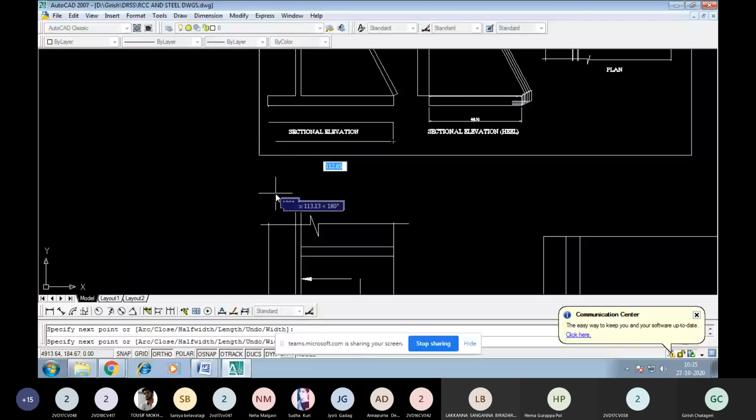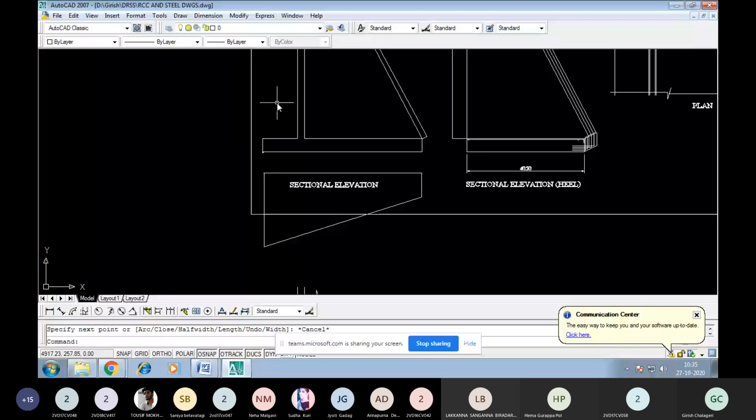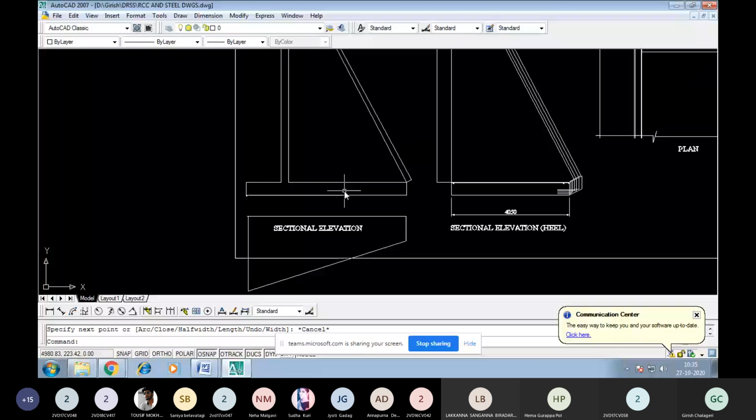This is a downward force. Definitely there is no load over this. So the toe will be designed for the uplift pressure, which is maximum at the bottom, while the heel slab, we can see the downward force will be more. So it will be designed for the downward force. So the reinforcement pattern will be the same as we did in the cantilever retaining wall.